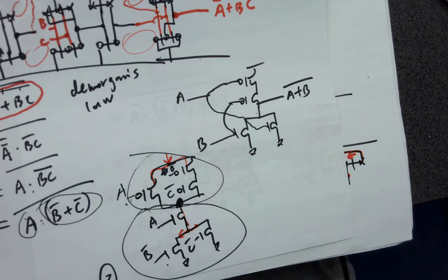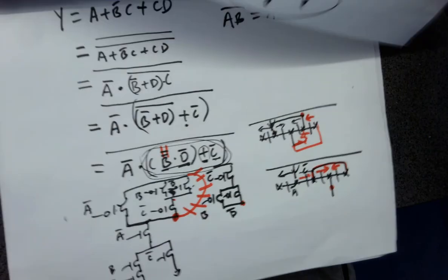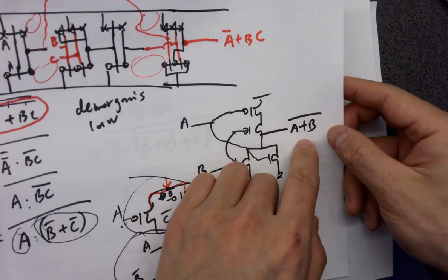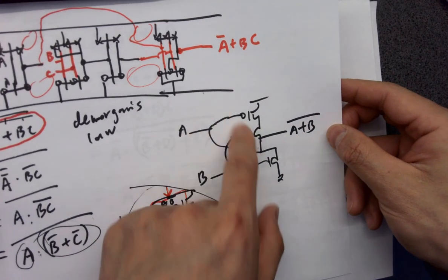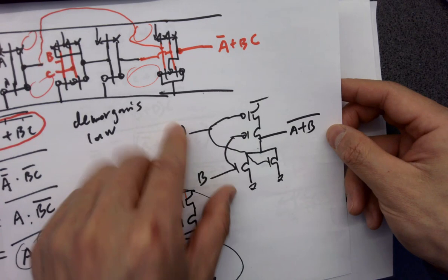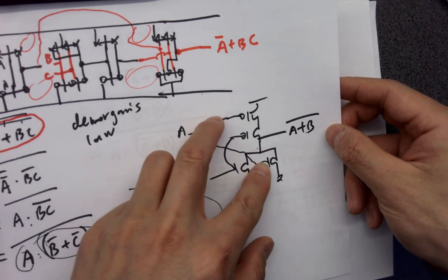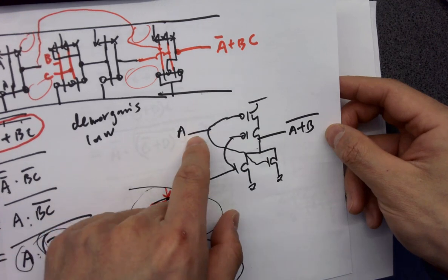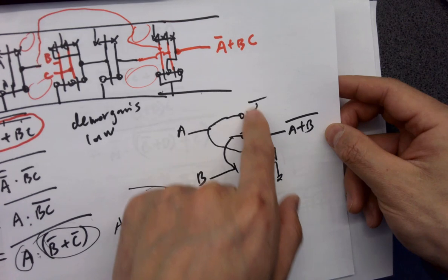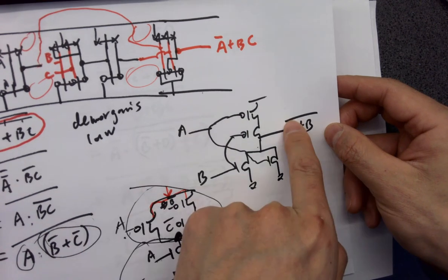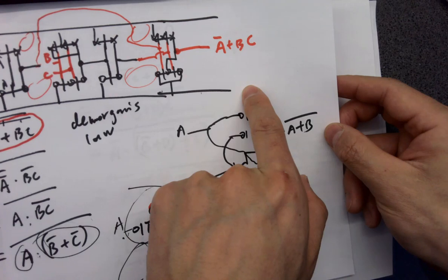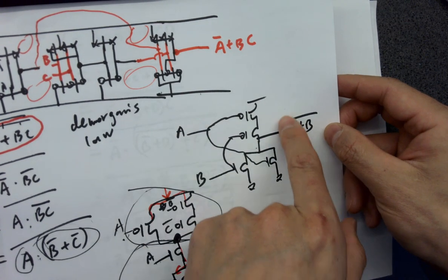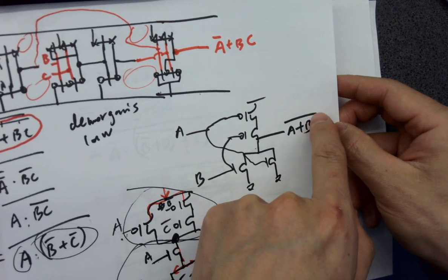We can use this model to find out all the other more complicated circuits like this. Because we know this kind of structure, every time the PMOS are getting a zero signal, because all the signals are being shorted to both PMOS and NMOS, whenever we have a zero input, it's always turning on the PMOS. So zero input, you are getting a 1 because it's turning on the PMOS, putting this up to 1. Okay, so that's why it's always getting inverted, and that's why the logic eventually gives you this kind of structure, because you have a bar on the top always.